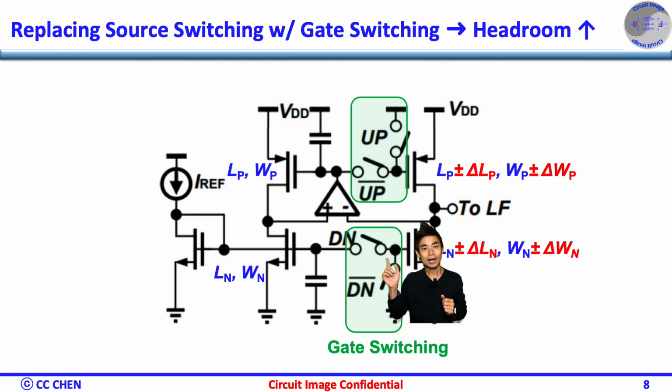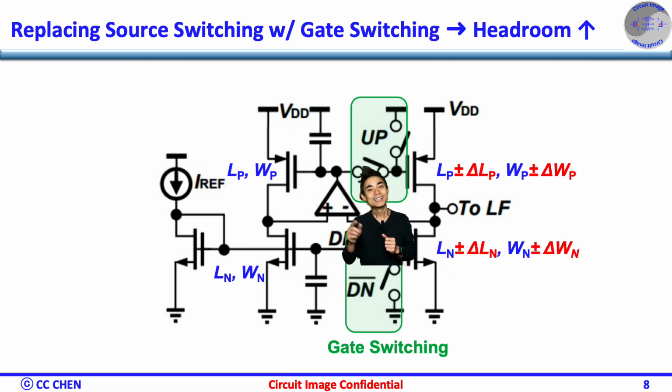In addition, the up and down switch may be much faster than the source switch now, such that we could reduce the turn-on time for the overlap time that you need in the up and down paths. Then we will reduce the charge pump noise further. Please be advised, the gain boosting still reduces the up-down current mismatch in the balancing here. But if there is a device mismatch for the local variability, the current tracking ability will be limited.